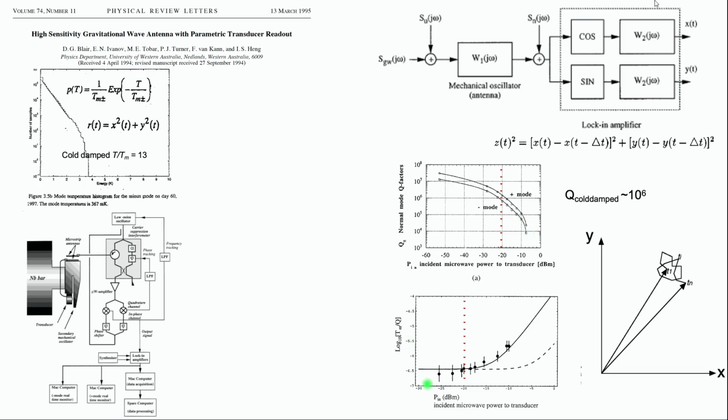The problem was that amplitude noise would then act back on the system, and it looked like thermal noise, and it would go up. So this was an optimization process, so we had to pick a power before that occurred. But we knew how to make our sources lower AM noise, so that could have been pushed out if we had a chance to improve this. So there's a whole bunch of noise sources, and you can sum them up as narrowband and broadband. But when your transducer is kicking this, it excites it like a thermal noise, and it's narrowband. And so we showed that.